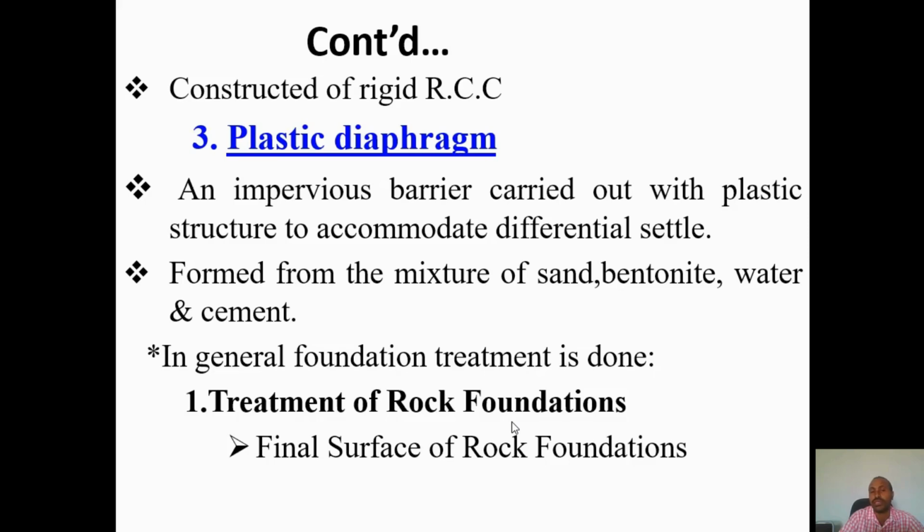And plastic diaphragm is the last foundation treatment, an impervious barrier carried out with plastic structure to accommodate differential settlement. So plastic structure is formed from a mixture of cement, sand, bentonite, water, etc. You mix them, and you can create a plastic sheet, an impervious barrier against the flow of water.